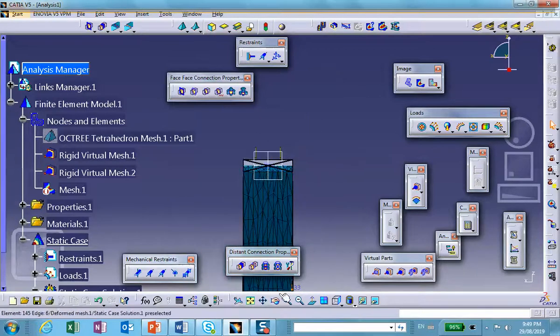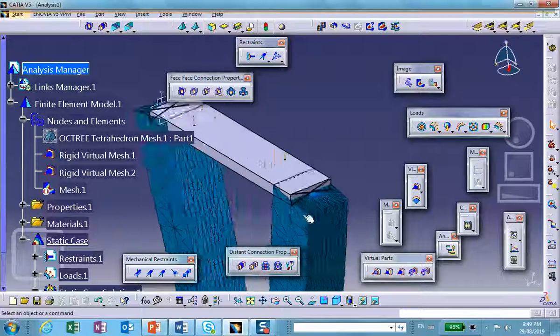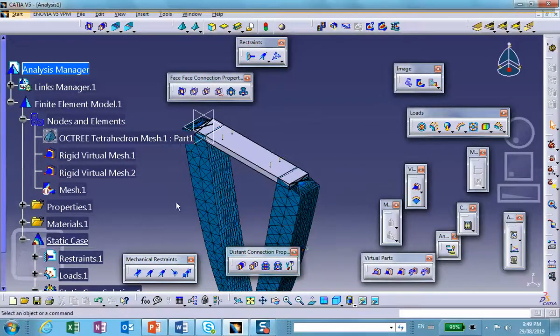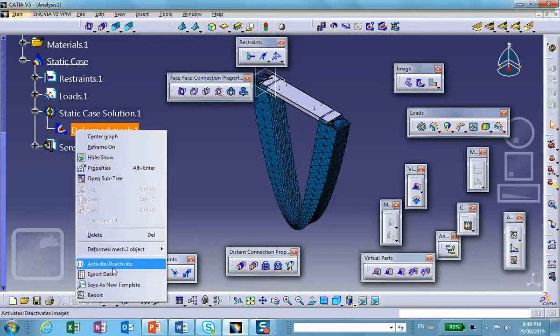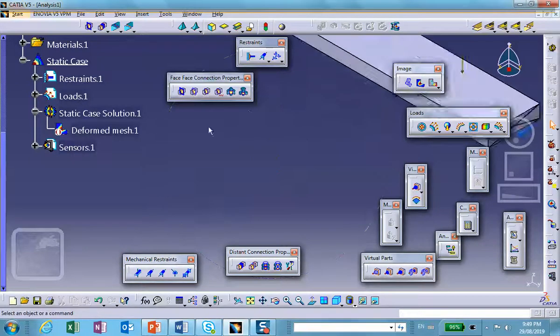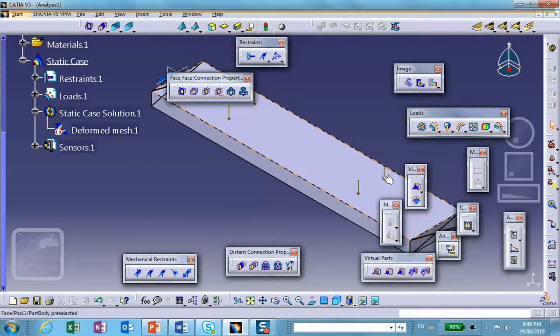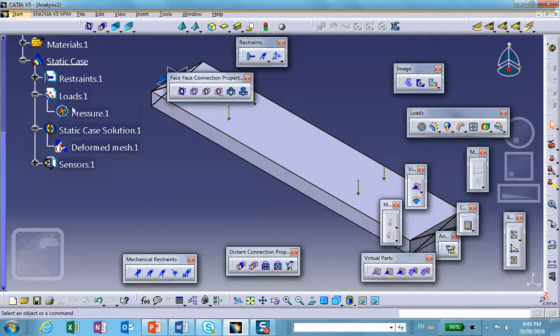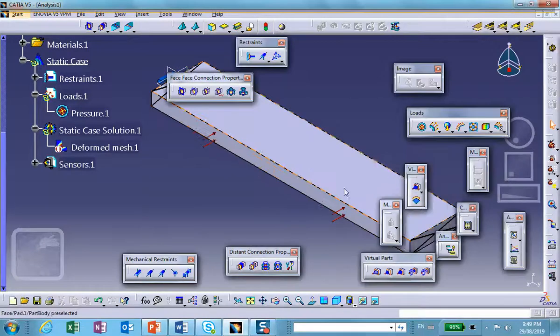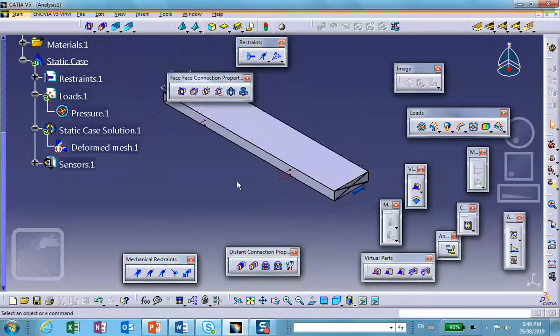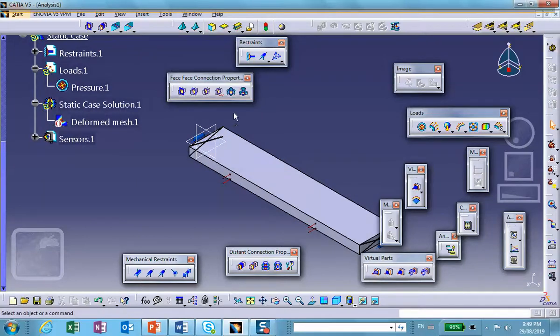But when I change my loading direction, you will actually see what happens to that sliding pivot. So let's go back here. Deactivate this. Deactivate that. This time take the load that I applied, and instead of the top, let's apply it on the side. Okay, so we have a pivot here, which means it will not be allowed to slide. It will be allowed to rotate.